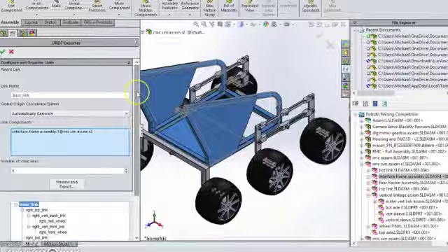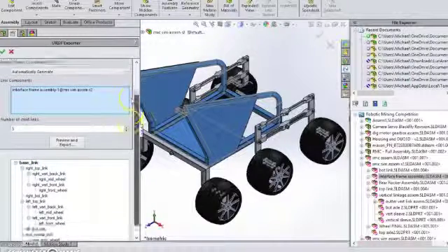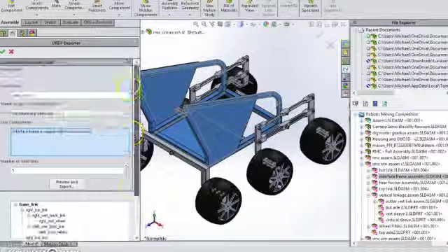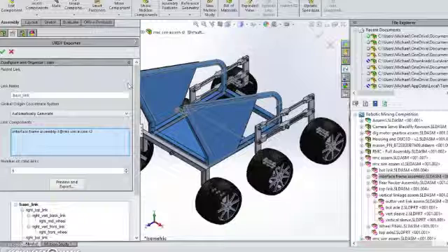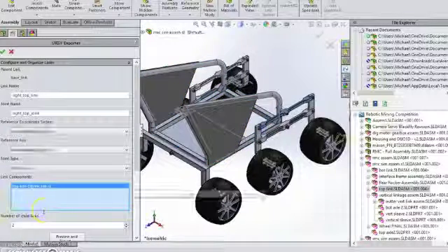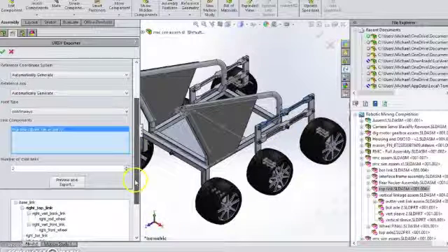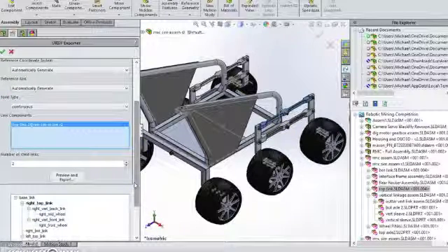Now I pre-prepped this export, though when you're doing it yourself, it's a good idea to build it piece by piece. For instance, you go from the base link to one of these right top links and then work your way down and see if the axes that you create, the joint locations, are correct and everything is coming out correctly.